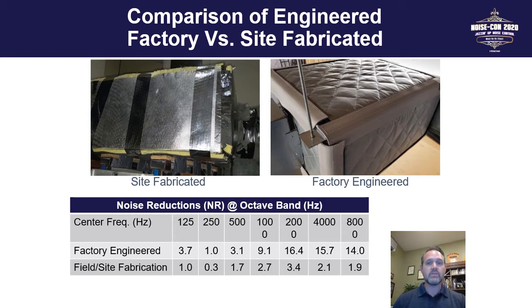So from this testing, the critical factors that came into play were that it really is a function of the design, and making sure that the sealing of the edges and corners is done to maximize your performance. And also, if you're going to apply a jacket to this type of equipment, it has to be removable and reusable. It's not enough to just install it the first time if it's not going to be installed the same way the second time, or you'll never realize that overall performance down the road and in the future.